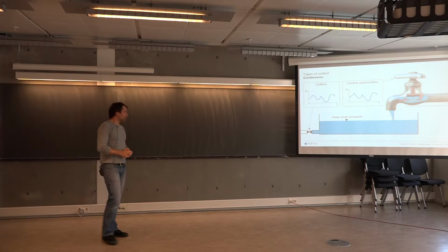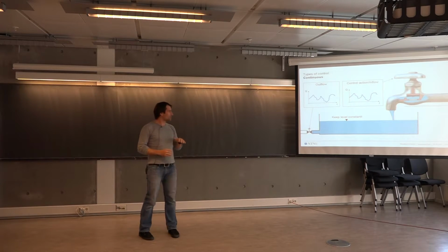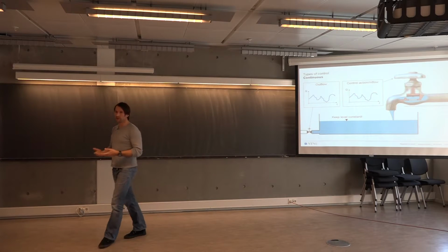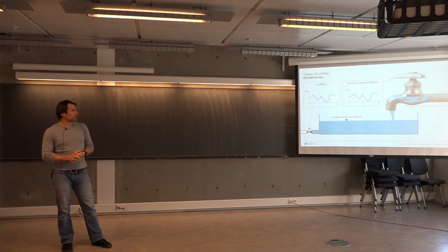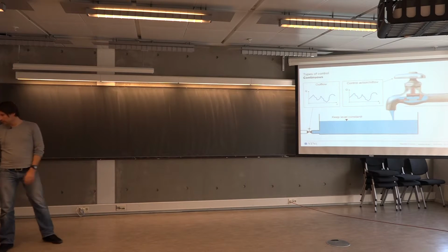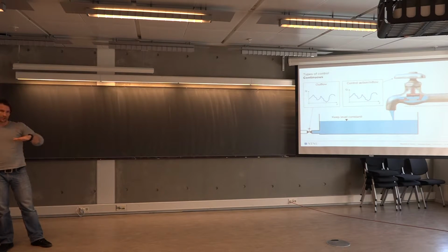And if you want to keep that tank level really constant, this may be the better choice. However, it depends on many factors which one is best. I guess such a valve is a little bit more expensive than the other one. So if money is the main thing, you might want to go for a cheap valve and accept a sort of unsteady tank level rather than something really precisely controlled.